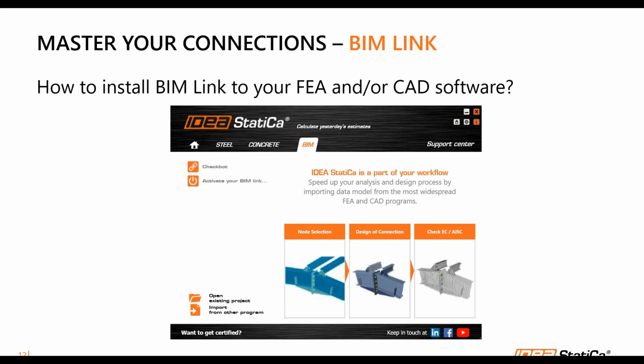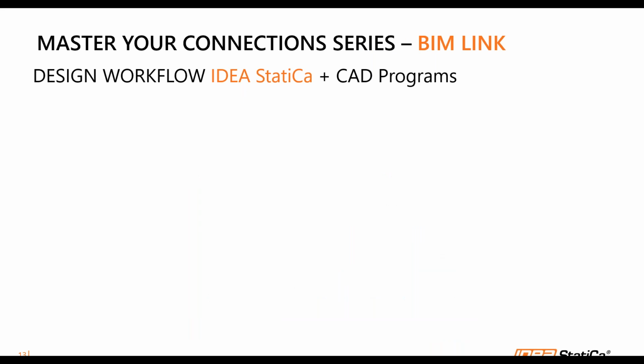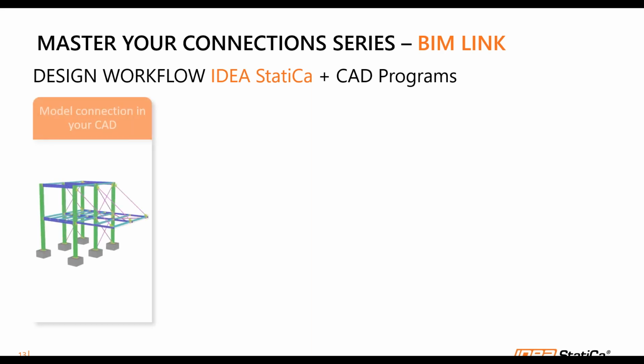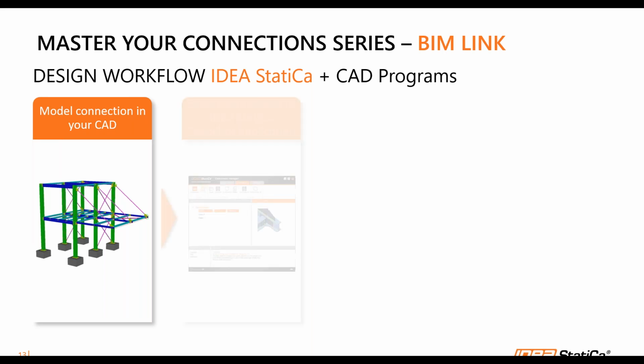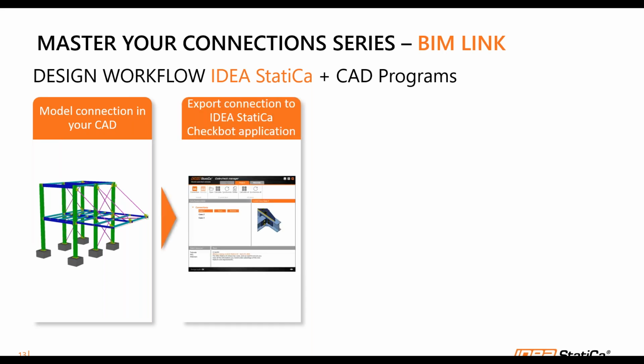So once we have installed, all this information will be available on your PC. I will now show you the basic design workflow of IDEA StatiCa using your CAD programs. For example, you have Trimble or Tekla Structures, Autodesk Revit, or probably Autodesk Advanced Steel if it's more common. What IDEA StatiCa captures is the geometry, the profiles, and the shapes of the sections.